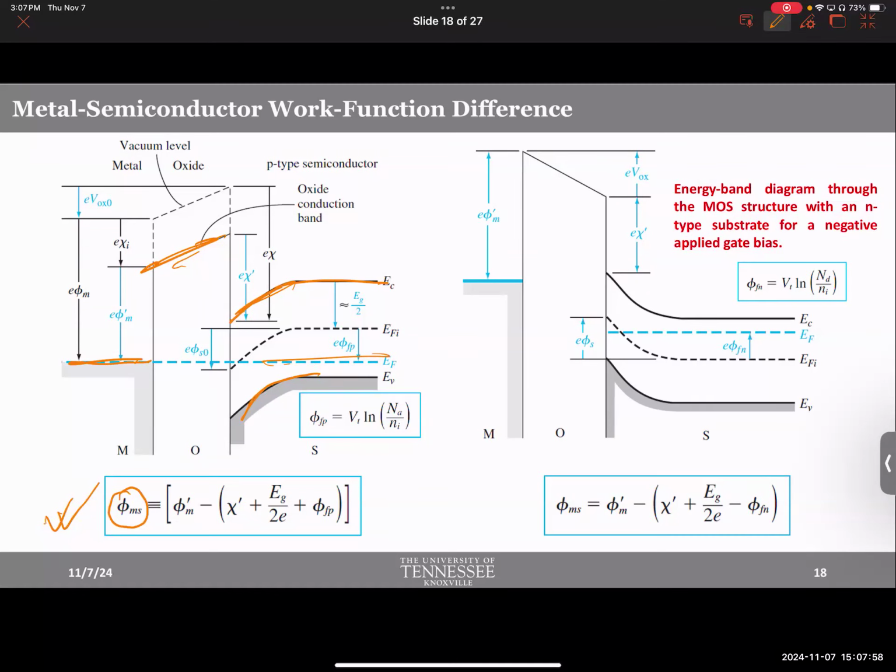You might be wondering what's wrong with bending. I mean, it's okay, let the semiconductor bend. What's the big deal? Did I tell you whenever there is band bending, there will be charge accumulation? Okay. So apparently that charge will have an effect on the device property. If you connect random metals, there will be different kinds of bending. For different metals, there will be different amounts of bending. So you have to find a way to quantify how much bending will occur in the material.